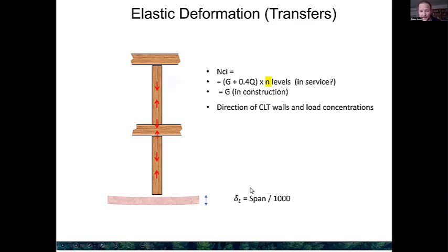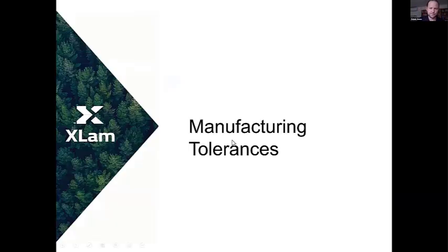So when we're designing for span on 1,000, we're going to have this initial dead load deflection. So your construction case will be different to in service, and it might be pre-cambered. So again, understanding the nuance about in-service versus the construction case.